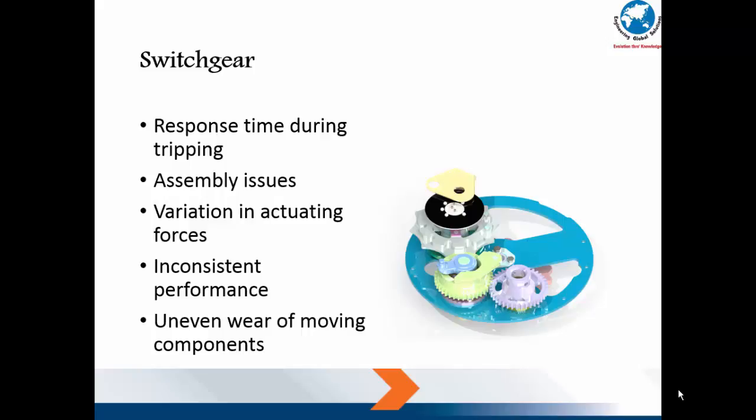Take the case of this switchgear in question. The response time during tripping is absolutely a critical to quality parameter. Assembly analysis: assembly issues during integration of the parts would always be an issue. Variation in actuating forces, inconsistent performance, uneven wear of moving components.